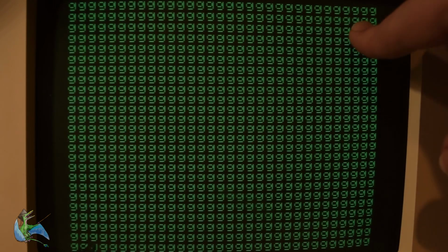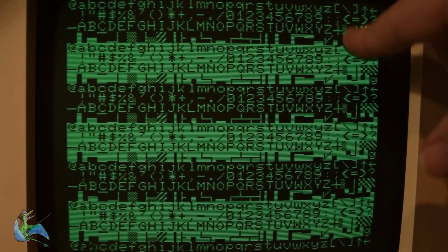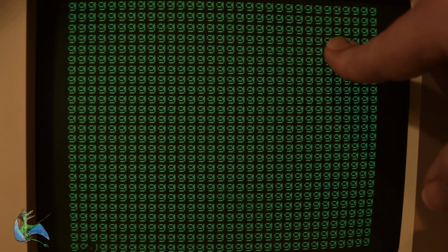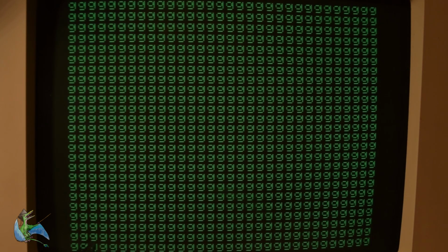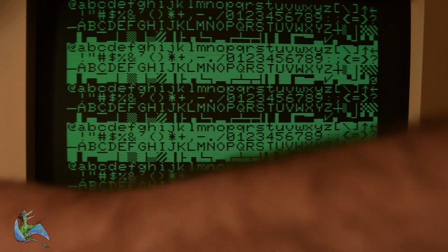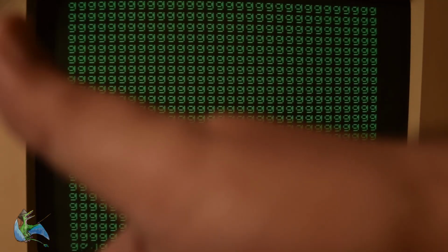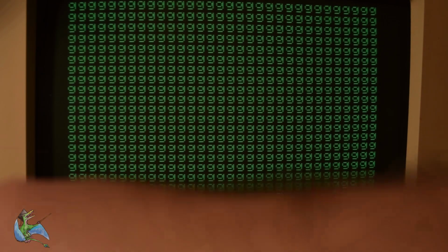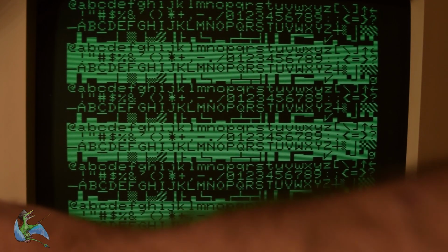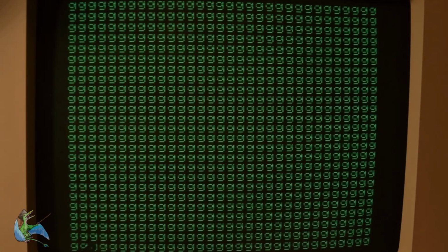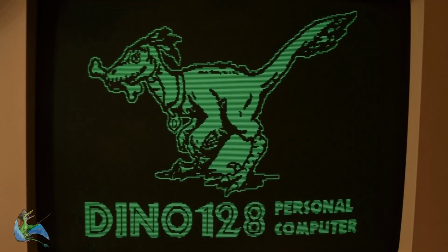And now this is the 6 megahertz clock, which means the CPU is now running at 1/8 of that, like running at 0.75 megahertz. Now, if I grab this and put it back, this needs to be debounced before it's going to be reliable, because it just directly changes it. So occasionally I crash it if I try switching the turbo switch. You can see it sped up a lot. So now it's running at 3 megahertz instead of 0.75.